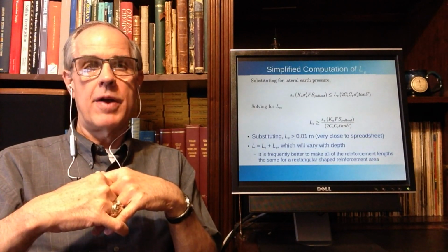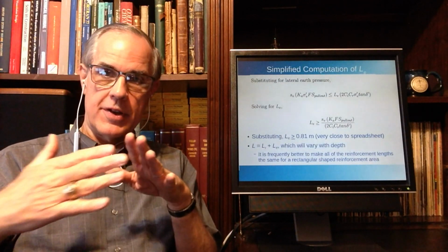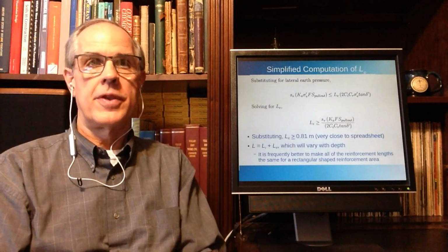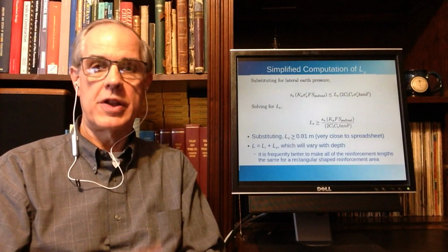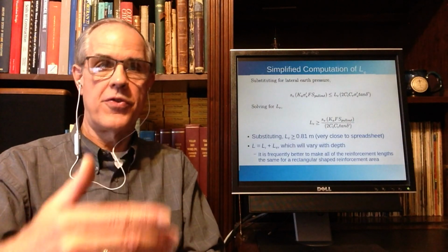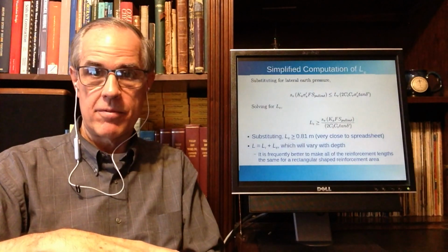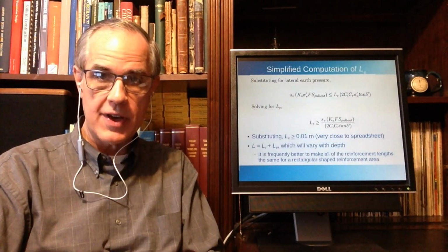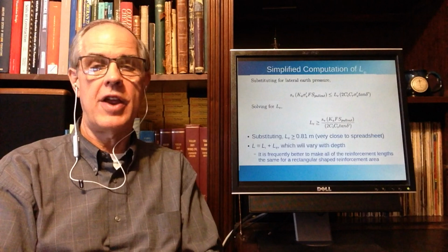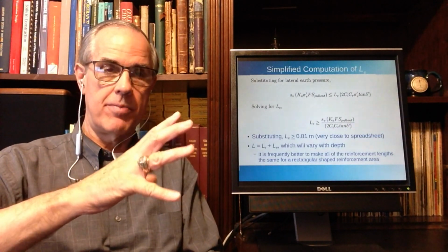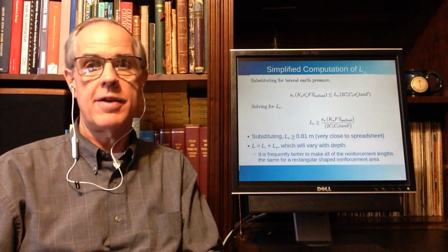To fix that problem, the easiest way is to lengthen the strips further back to include more soil, and therefore increase the resistance both to sliding, because you'll have more weight pushing down and more foundation area, and to overturning, because you'll have more weight to resist being overturned by the retained backfill.